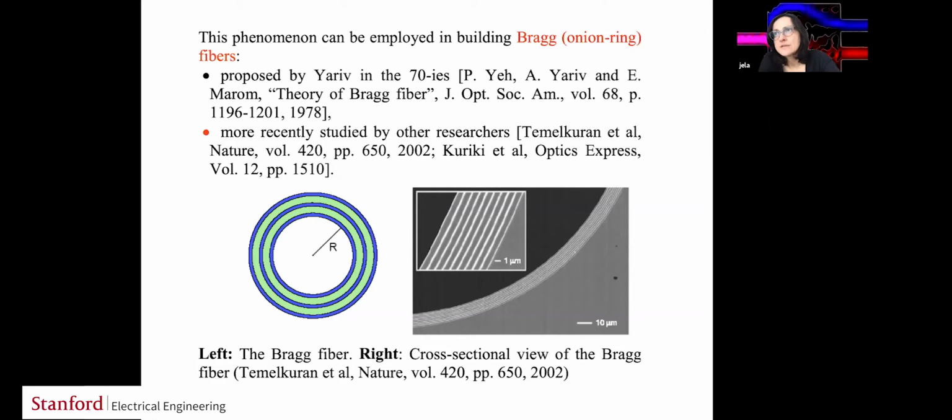Around the periodic axis, it depends on what you want to do, right? And we will do that later on when we talk about what we call micropillar cavities, which correspond to what you're talking about: a one-dimensional distributed Bragg reflector, but with finite extent in the other 2 dimensions, okay? That's basically what you're talking about, right?